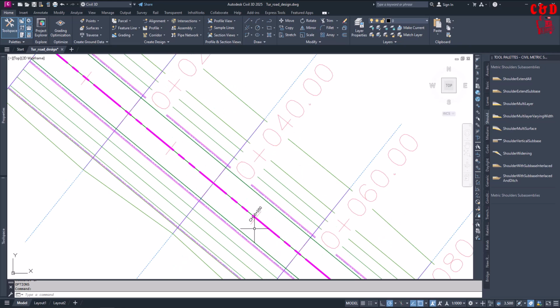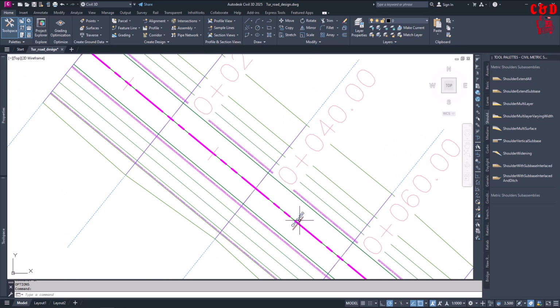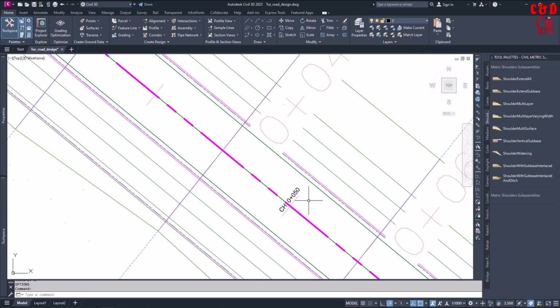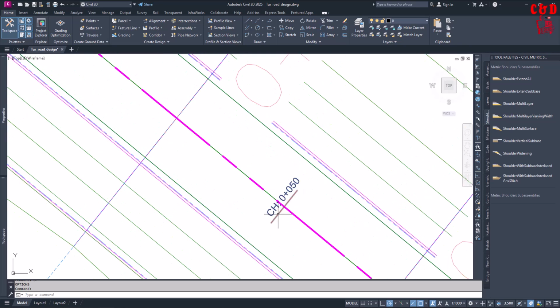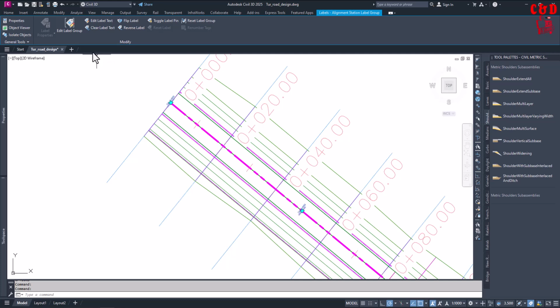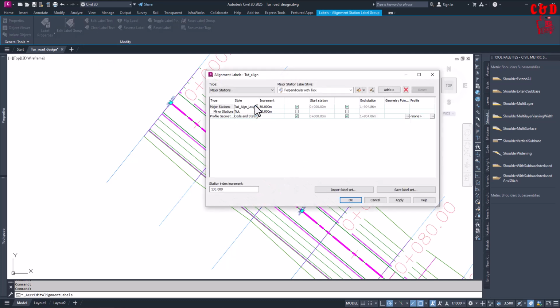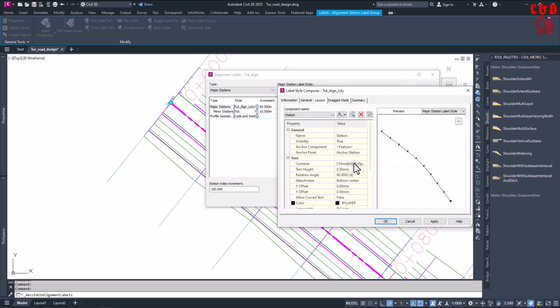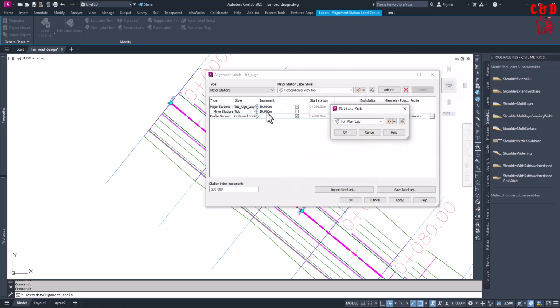Now this is here. I guess it would be great if it occupies the entire width of our road. So let's click again on the level group, and then again go here and click on the alignment. And we don't want this increment actually at 50, because it's too long to control our alignment.